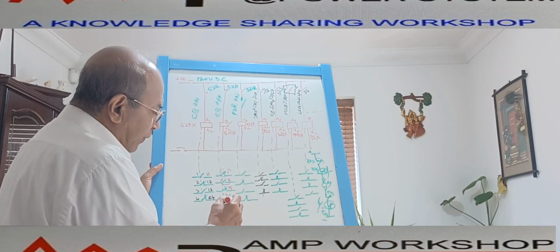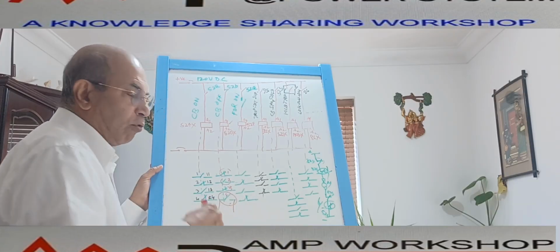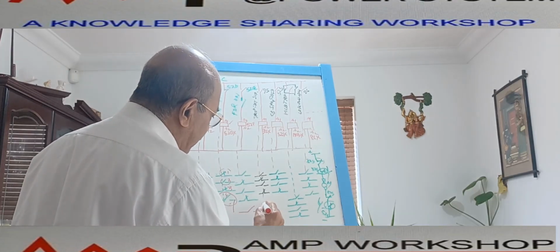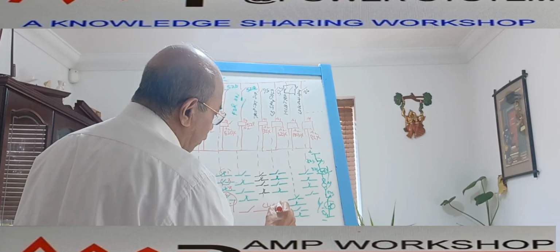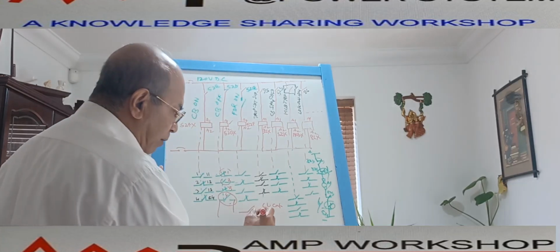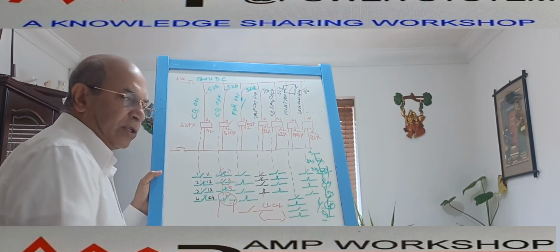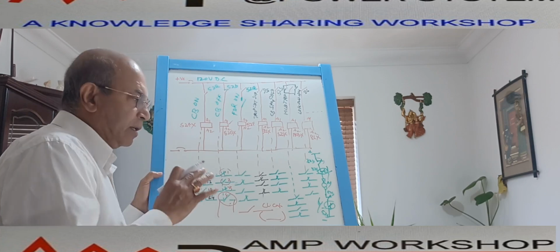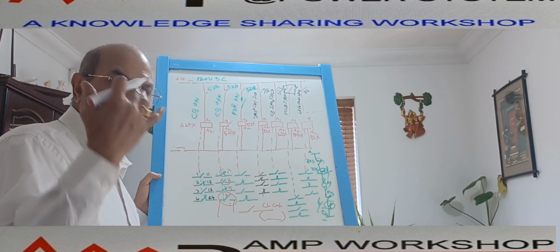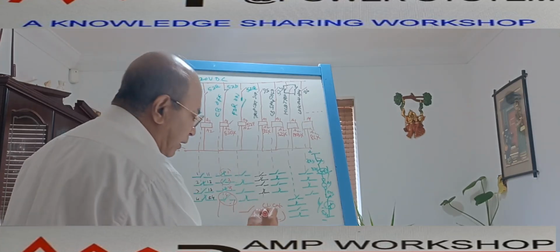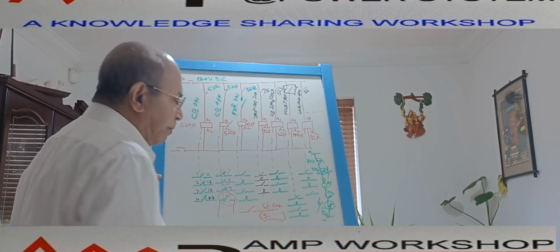So what do I do? Suppose we are using this contact in the closing circuit. Here we represent it this way. Suppose it is going to the closing circuit. From here we can make out, and moreover, more clearly we can make a reference over here. Suppose the closing circuit is on a drawing page, because a switchgear drawing has multiple pages. Suppose this closing circuit is going to page number 3. We can write down here page number 3.